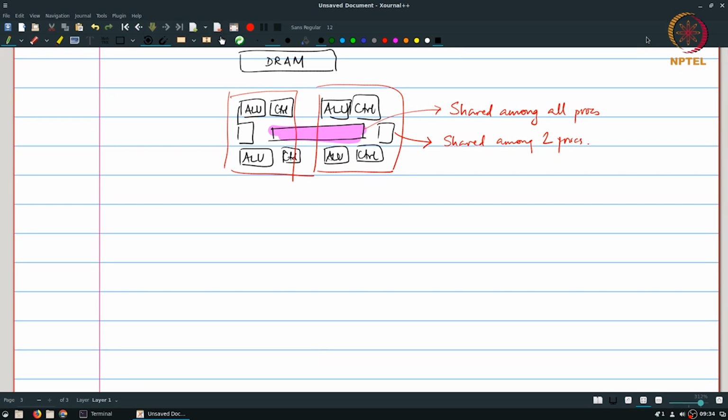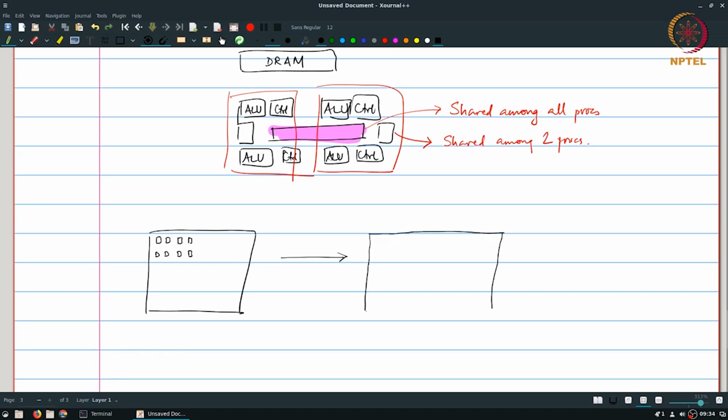So how do we make use of the observation that image processing typically has a very large amount of parallelism? In other words, each pixel could potentially be processed independently, or at least simultaneously with a lot of other pixels. So the architecture also should reflect that kind of structure. The architecture that the GPU architects came up with looked similar to the pixel array that exists on an image. So rather than having large ALUs, large control units with some amount of shared cache and an interface to DRAM, the structure that was adopted was something more like this.